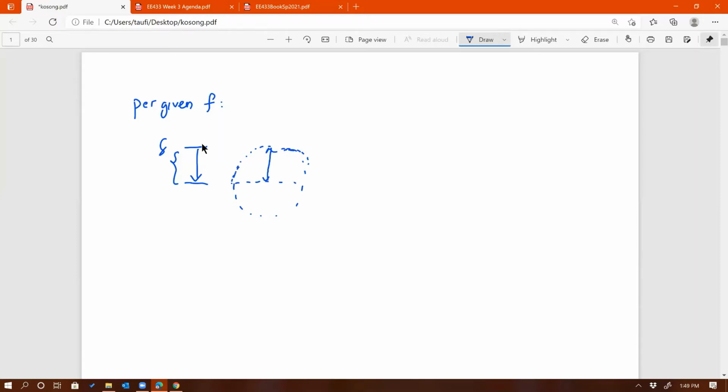Ideally, theoretically, if they are the same, then you're practically covering the entire surface. But to ensure that you are covering the entire cross-sectional area of the wire, you want the radius to be smaller than the skin depth.